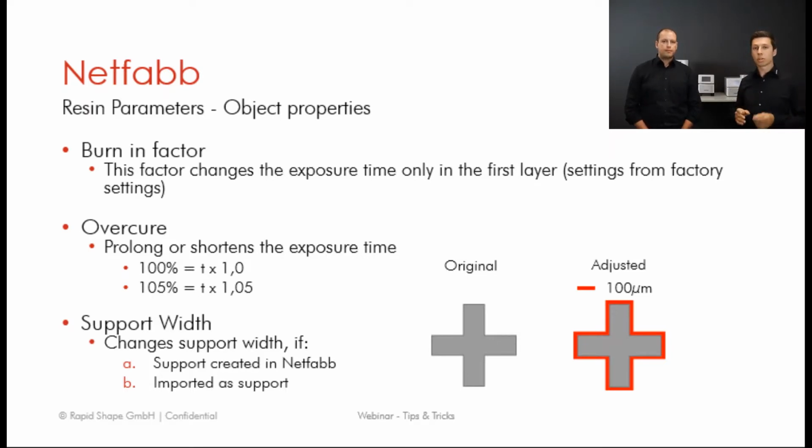Most important is the connection area from the part to the support and not to the platform. Because the platform, if you're using, for example, our scripts, you should not adjust anything. Also, in the scripts you can see the platform connection is way thicker than the connection to the part. So be careful changing things in there, just so you know what is going to happen.